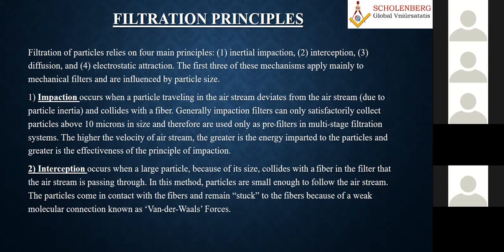So the bigger ones will all be filtered and not allowed inside. So they are used only as pre-filters in multi-stage filtration. So this is impact, the first part. The higher the velocity of the airstream, the greater the energy imparted to the particles and the greater the effectiveness of the impact principle, because the more the energy, the more they will hit and the more will come down.